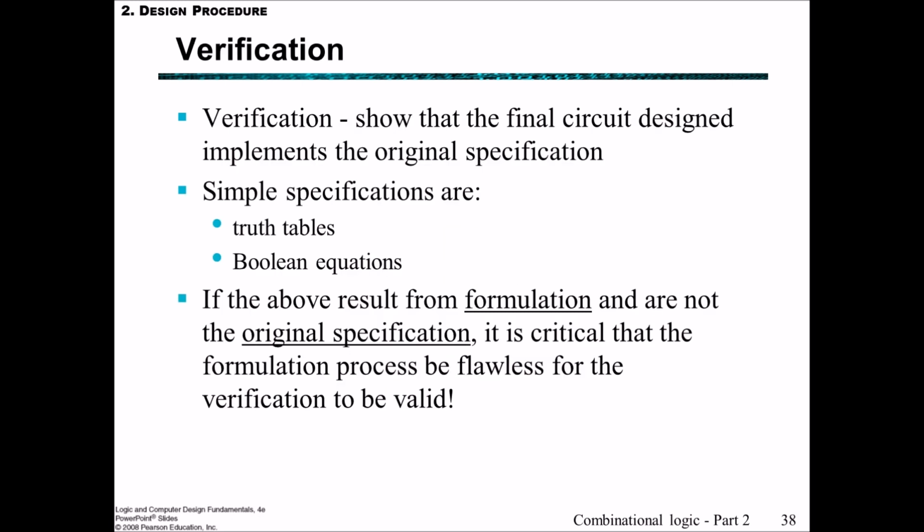The next stage of our design procedure is the verification stage, where we compare the final circuit design implementation and the original specification. And if we've had to do steps in formulation in order to create truth tables and Boolean equations that are not in the original specification, then we have to be very, very sure that the formulation process is flawless for the verification to be valid. We're trying to verify the original specification, and so if we've taken steps between specification and formulation that may have introduced errors, then we don't want to be verifying our potentially incorrect formulation.